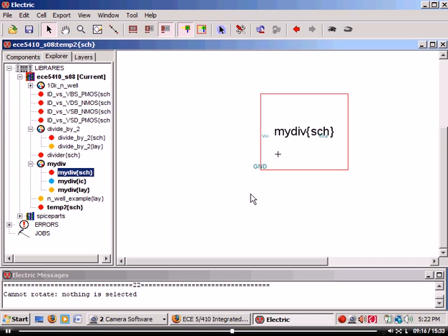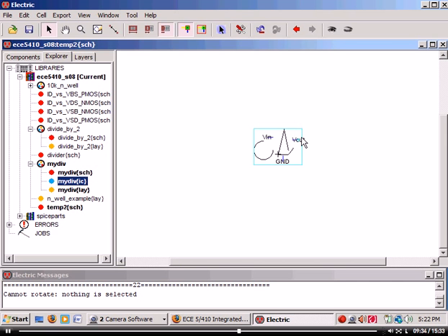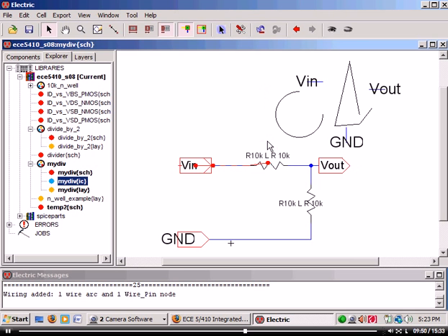Oh, okay, it didn't tell me. A lot of times it'll tell you, don't you want to really copy the icon in here instead of the schematic? And yes, I want to copy the icon. But let's delete that and then use my icon, drag it in. Then I can connect up my wires. Now notice the name went away, so if I want to see the name after it's connected, I got to put annotation text there. Connect up here, connect up there, and there my symbol for, let's do a Control down, moves down into the hierarchy to the symbol that I drew.